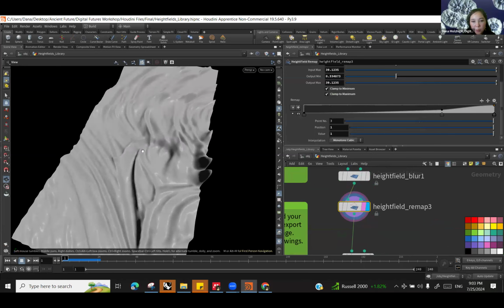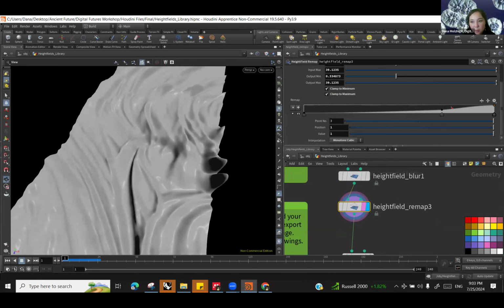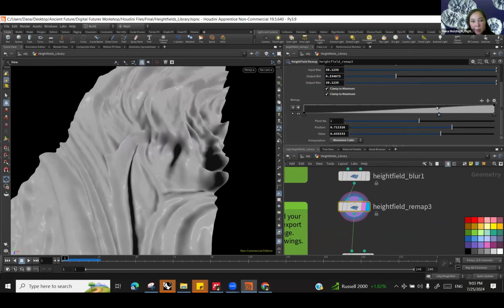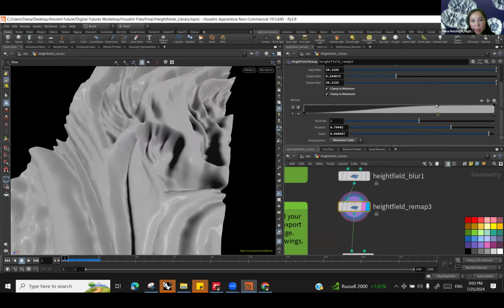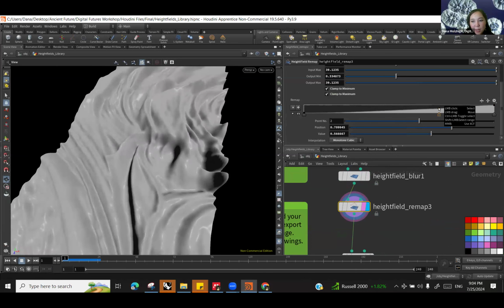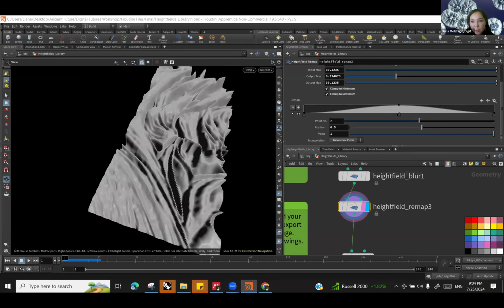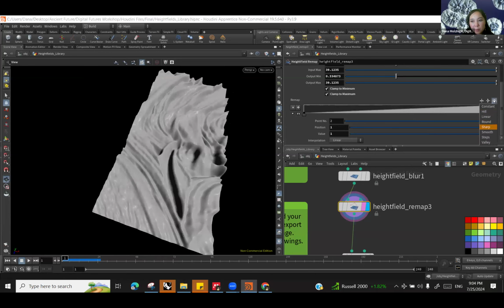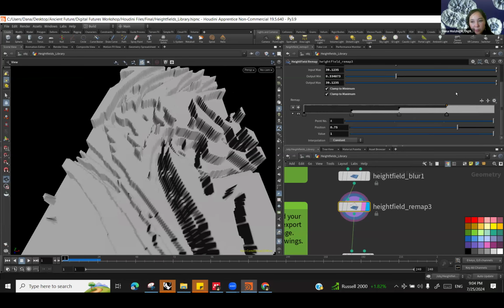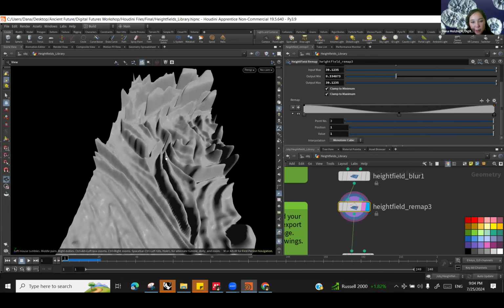Okay, so you can remap the values as we discussed earlier. This is the value that I really preferred. But because it works only in height and mask, you cannot unfortunately manipulate this in a 3D volumetric way. But we can definitely work with heights. So you can remap it using the default remapping tools like Heal, Linear, Sharp, Smooth, Steps, Valley.